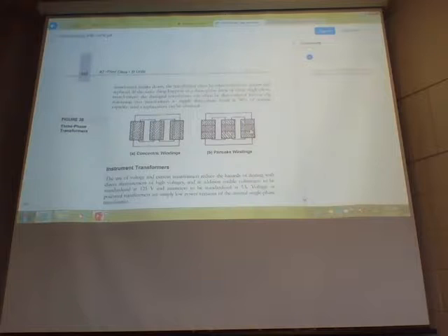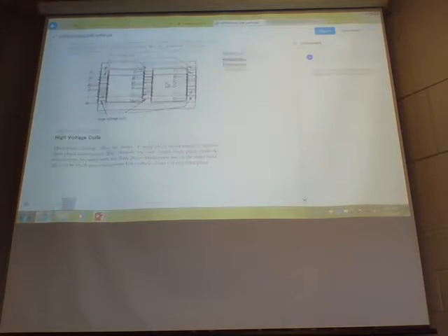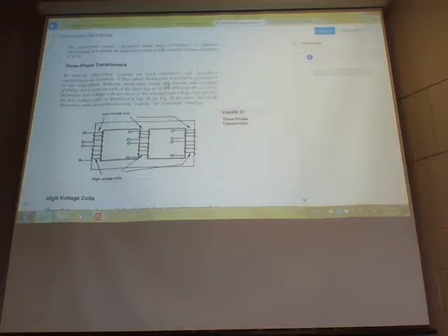And there are different ways. The concentric windings, you have, so in practice, low voltage coils are closer to the iron and high voltage coils are over low voltage coils, and 38A and B shows one of the alternative methods sometimes used, pancake or concentric winding.